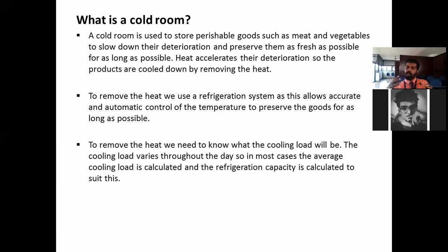Understood? If you want to remove the heat, the first thing is that we need to know from where all this heat is being generated. That is what we are going to find out, and we will be getting its amount in BTU per hour. Then we will add all the BTU per hour, and that will be converted into TR. So that much heat has to be removed, which means that much conditioned or cool air should be given to that particular space. Understood? Similar to what we have calculated in the heat load calculation, the same thing.